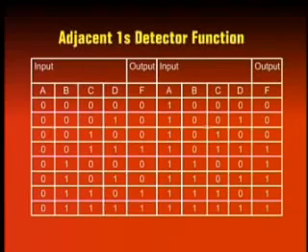How many OR gates are required? Since it's a sum of product implementation, all the product terms have to be summed together. So a single OR gate is required. The OR gate has 8 inputs. Some NOT gates are also required to implement complemented literals in some of the product terms.